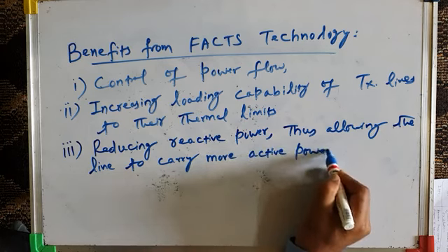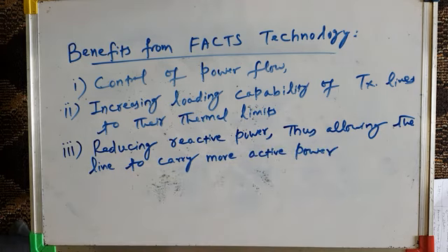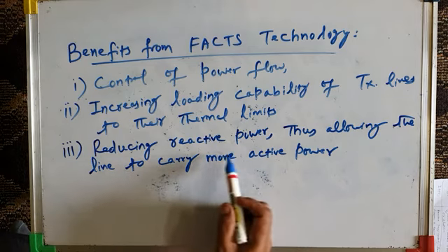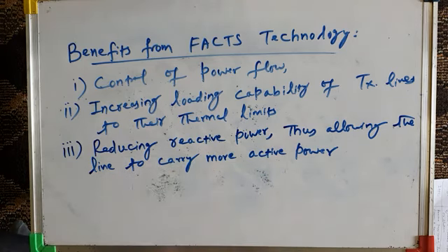Because using a FACTS controller, whether it is a series FACTS controller or shunt FACTS controller, or a combined series FACTS controller like IPFC, or a combined series-shunt FACTS controller like UPFC, with the help of these FACTS devices, you can control or reduce the reactive power flowing on the line.